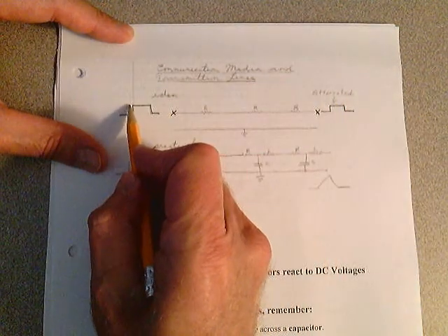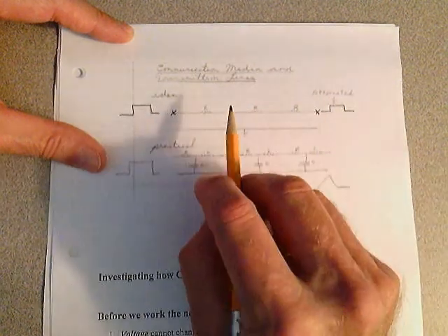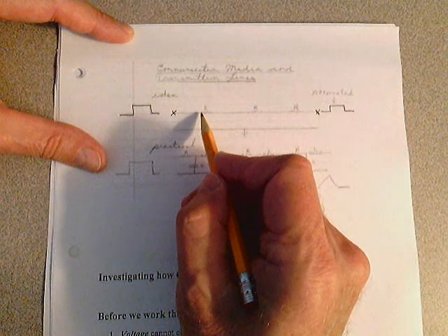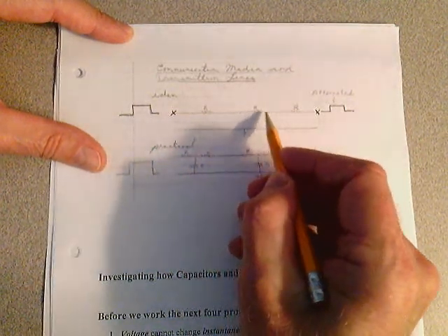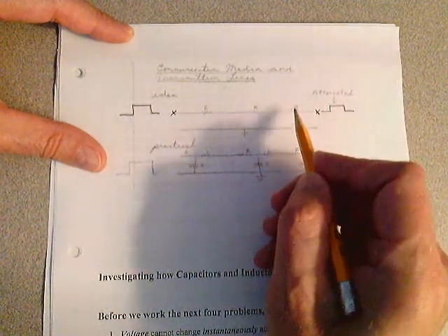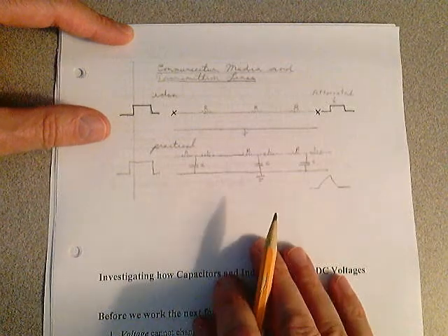So notice you might have 5 volts here, but by the time you get down here, you may only have 4 volts or 3 volts. That's due to the voltage losses in the distributed resistance, and we're showing it as resistance here and resistance here and resistance here. Usually when they model that, it's so many ohms per feet.